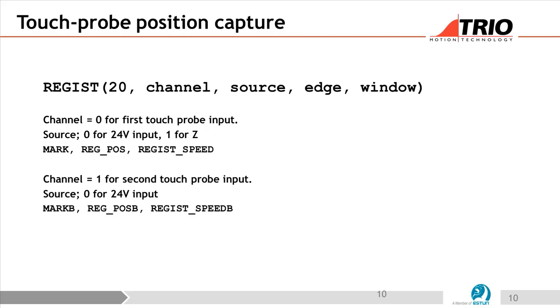But I know some other drives don't. Commodore also has the input. Yeah. Most of the drives. Yeah, we have an old Kollmorgen drive here and it doesn't have the Z because I think there's no Z on the encoder on the motor. Yes, resolver. Yeah, so there is no Z. There are a few around that don't have the Z. And there are quite a few around that have only 1 input.